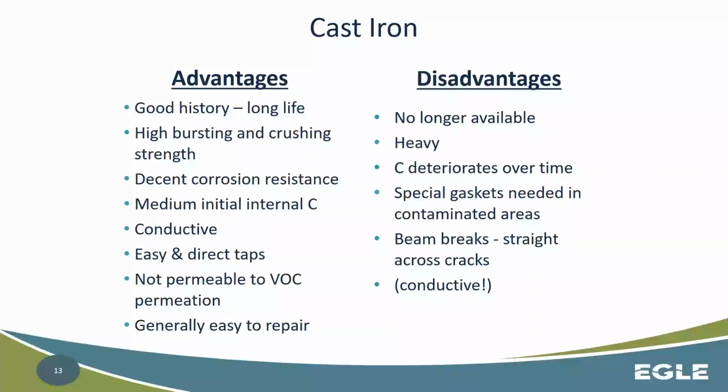Despite having high bursting and crushing strength, there is the factor that they can have beam breaks. So that's a straight crack across the water main, because they're very, very susceptible to that shearing. Okay. And then they're also conductive. So this is another aspect.